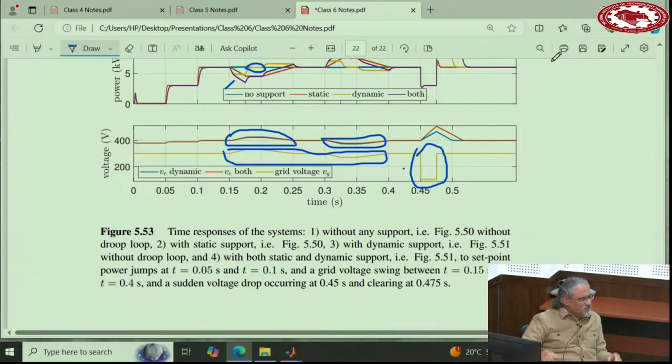And I told them, if you really want to get inertia, that means your capacitor is large, right? And then your R1 is large. Your gamma is a good number. So all these numbers mean that the responses of the system are sufficiently slow, these responses of the external loop, the inertia loop, that K3 is not going to really impact the response of the system. So the only case that you need to use K3 is if you are pushing the system to the extremes.